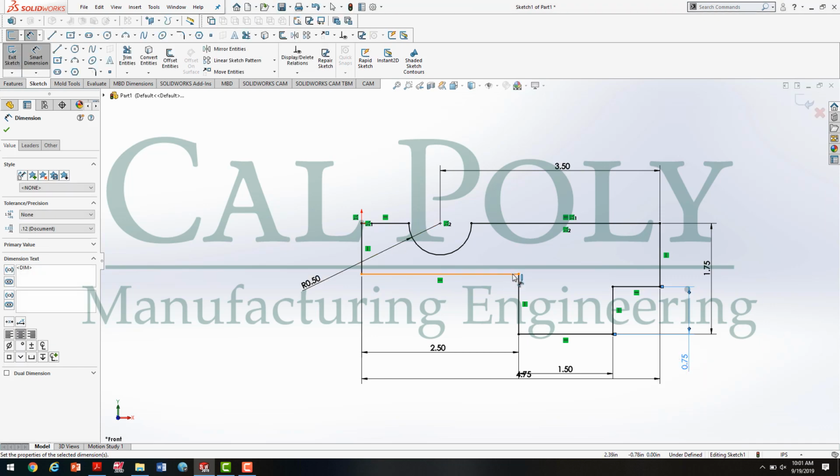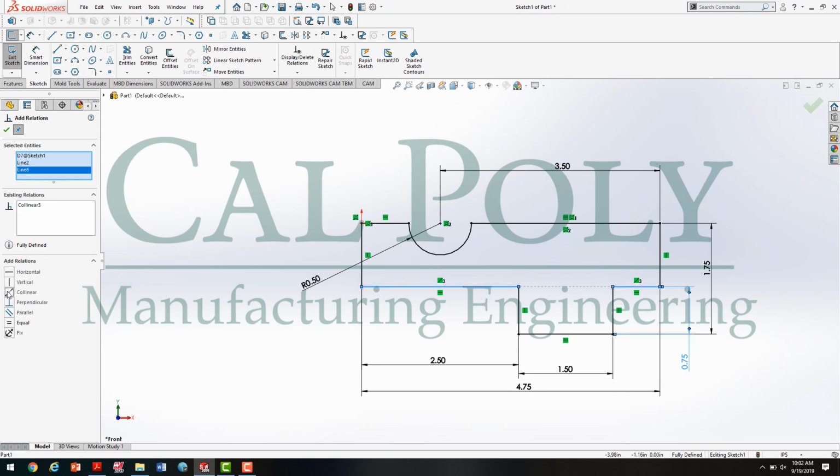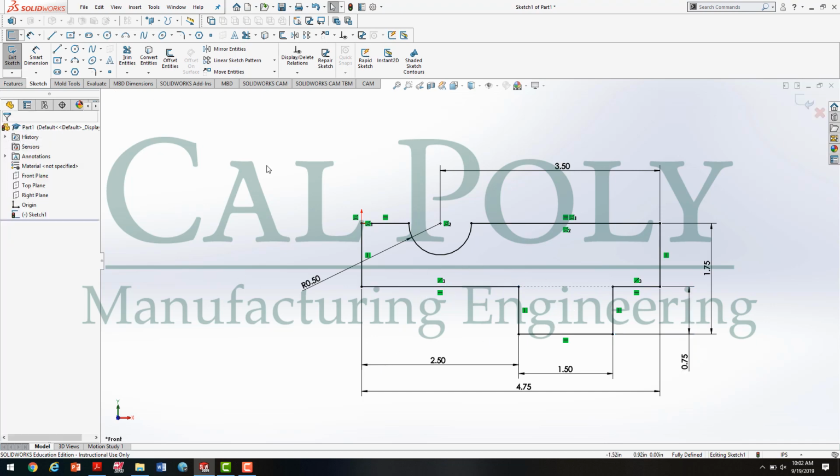The last but not least, we could dimension this line at 0.75 as well, or we could come up here to add a relationship. And if I click on this line and that line, I can make them collinear, which will end up fully defining the actual sketch. Notice everything is turned black. So I can use relationships by adding a relationship to define the sketch, or I can use smart dimension tools.